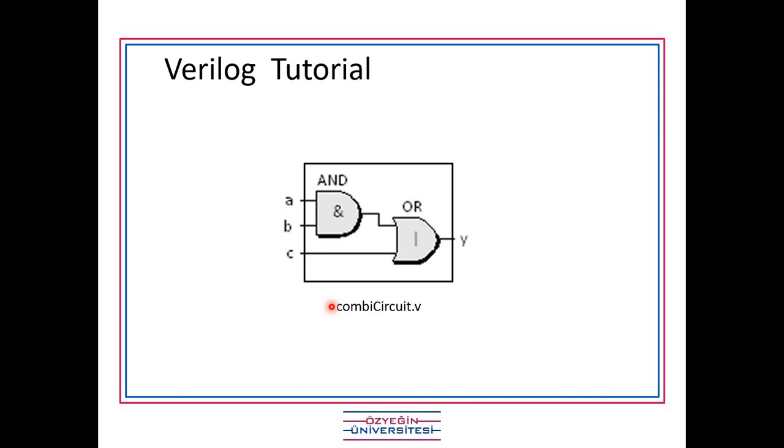So there are two ways of doing it. I will show you both of them in the demonstration of writing Verilog in the software. The first one is just by looking at what the gates are there, we just copy what is shown there. For example, we do A and B or C. This is the structural way of doing it. We just do A and B or C. We use the AND operator, we use the OR operator, and we equate it to Y. That is one way of doing it. That's called structural. And the other way of doing it is behavioral.